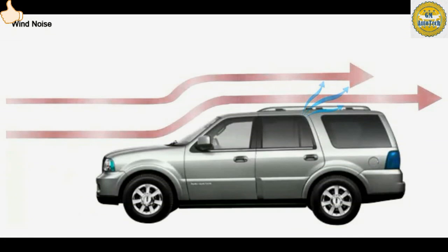Other noises are produced by wind, turbulence, and air leaks. Wind noises are caused by air escaping from the vehicle. Turbulence is air moving over or around loose or protruding moldings or between gaps in rubber seals, moldings, and drip rails. You may need to seal areas from which air escapes the vehicle or secure loose or protruding components.